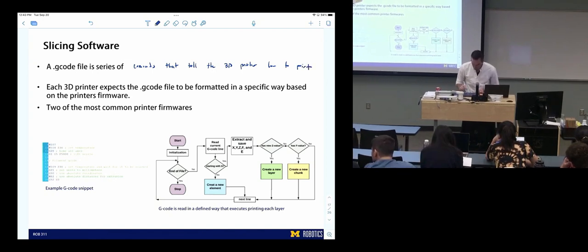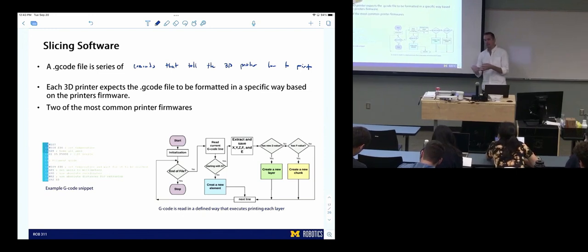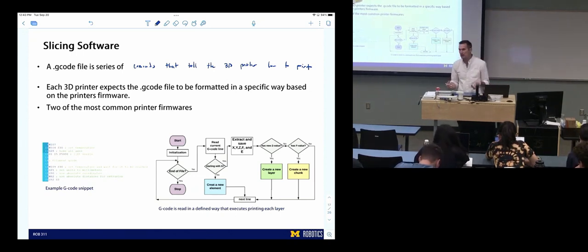What would be in G-code? What's the information? You have an STL file. I think you generally get what that's going to be. I think you know what a 3D printer is doing, at least globally. What is the G-code actually giving it? It's giving it every instruction, like when to extrude, how much to extrude, X, Y, Z, and temperature of everything. Yes, it's giving it all the commands for the toolpath, the speed that it moves between these, the temperature of the heating elements to extrude the filament. So it tells us all the general instructions.